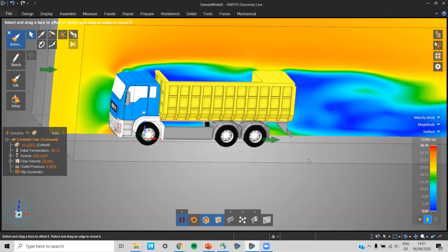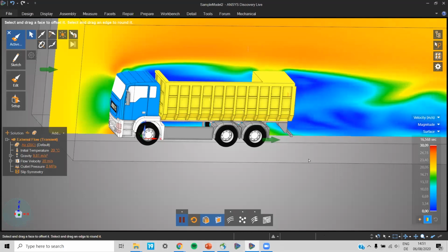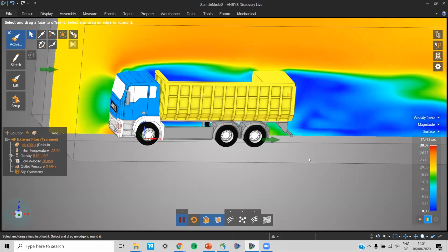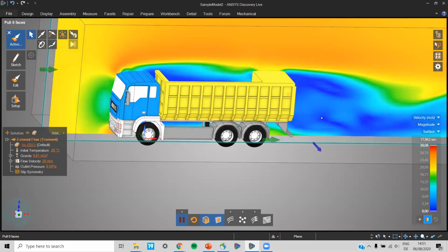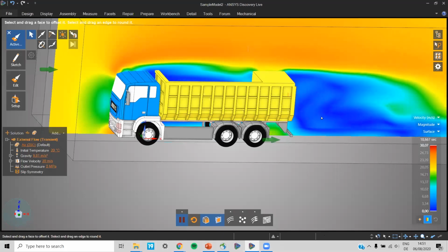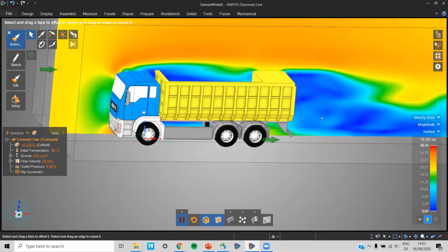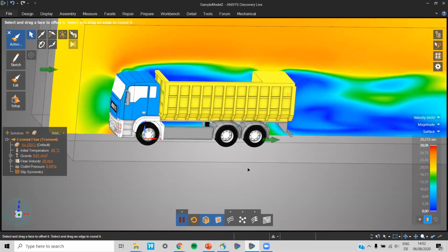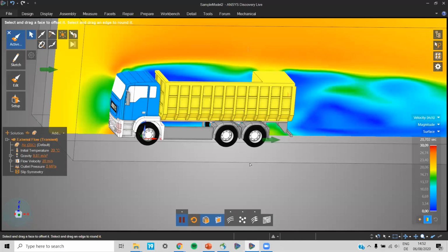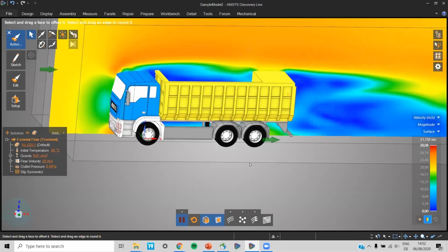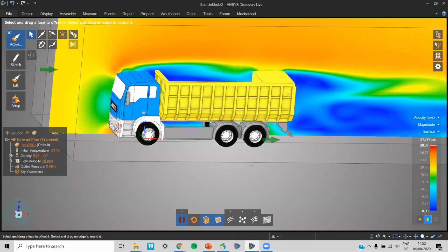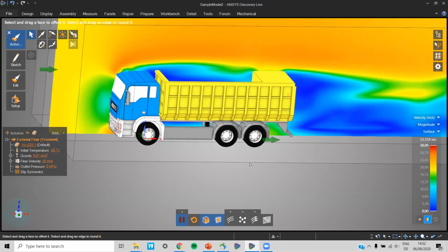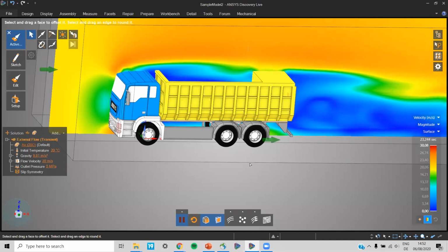So if you're working in additive manufacturing, you definitely have to create an infill and shell your body out to not waste material, because material costs are one of the highest costs in additive manufacturing, as you might know. So you have to create this infill, as I showed you in the bunny example. This is something that can be done with ANSYS. However, if you're working in metal additive manufacturing, ANSYS SpaceClaim is not the tool to generate these support structures.